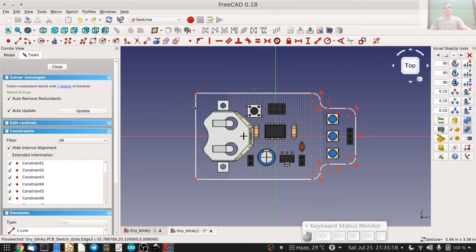So now we can add fillets at the two corners and a little cutout here and modify our outline. Let's use the fillet feature, like over here. Choose these two lines and then repeat it with the other two. Then escape the fillet feature.